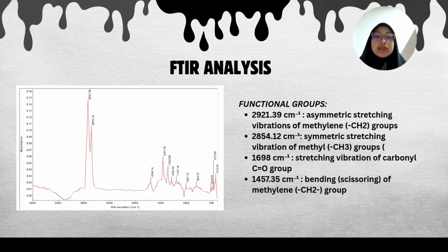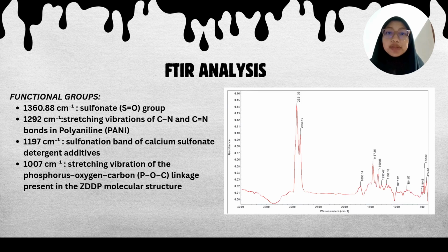Lastly is the peak at 1457 per centimeter, which indicates the bending of the methylene group. The presence of this peak further confirms the dominance of aliphatic structure in the lubricating oil formulation. Next, the absorption peak observed at approximately 1360 per centimeter is attributed to the sulfonate group, which is a sulfonate-based detergent in